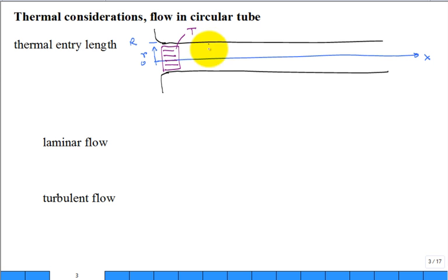And then a little down the wall, you can sketch it where the surface is warm, and then like that. So this is sketched where the fluid is being heated by a warm wall. And so you get this propagation of a boundary layer, until the thermal boundary layer as well as the velocity boundary layer is fully developed at a distance right here. It'll be fully developed thermally.